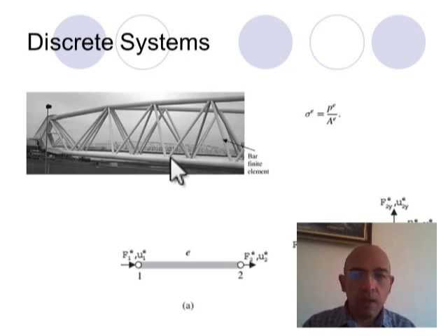A truss system only carries force along its direction. And when we want to analyze this truss system, one of the methods that we use is the node-based approach. Remember that we write the force equilibrium at each node, combining the forces coming from the truss elements.